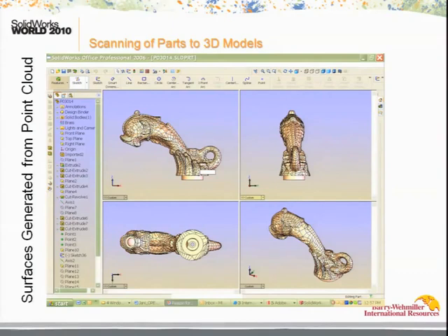That's a pretty difficult question to answer, because what manufacturing typically wants is for all the drawings that come to them to be in a single format or adhere to a single standard. But if you want to make that big a change in your standards, going from ASME to ASME is okay, but if you want to change from, let's say, ASME to ISO, there's a lot on the training part which you have to worry about. And I would say that is a more company-specific decision.